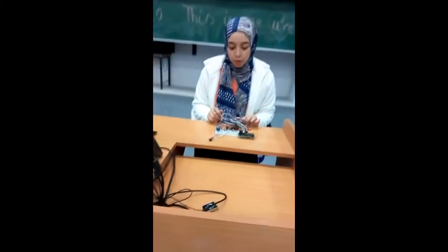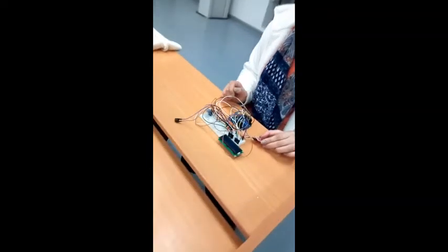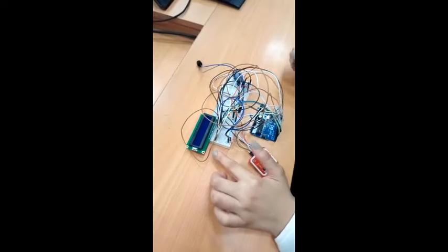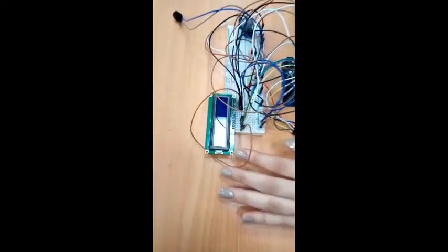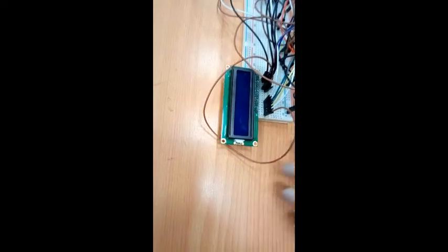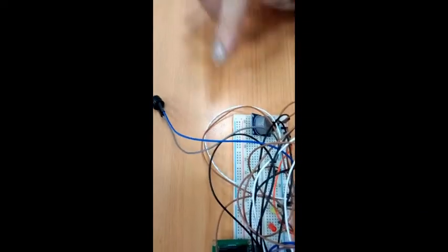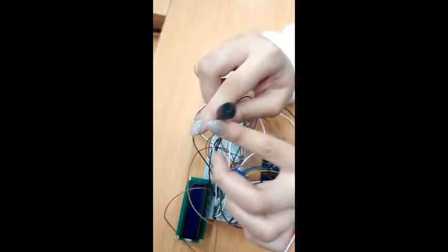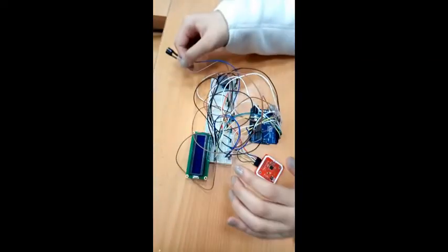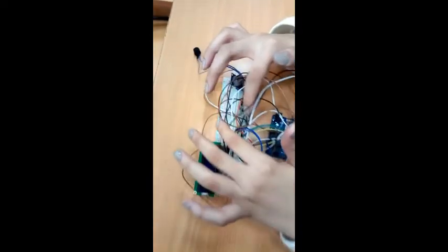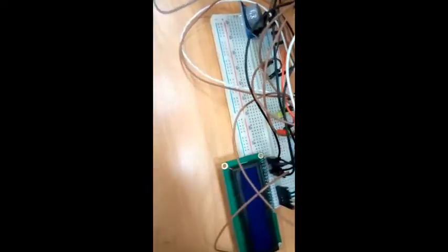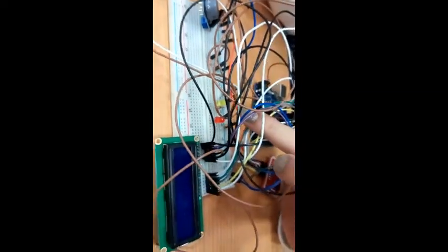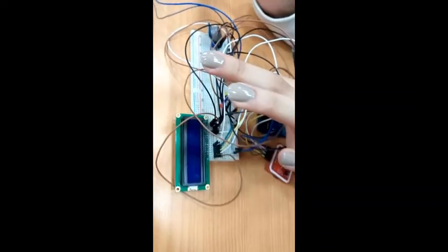We use in our project Arduino Uno. And our hardware consists of an NFC that reads the IDs of the students and the TA. We have an LCD that displays the count of students attending the session. We also have a smoke sensor that detects smoke in case of fire. And this buzzer makes a sound or an alarm if there's a fire. We also have two LEDs, a red one and a yellow one. The red one lights detecting that the door is closed, and the yellow one detects that the door is open.